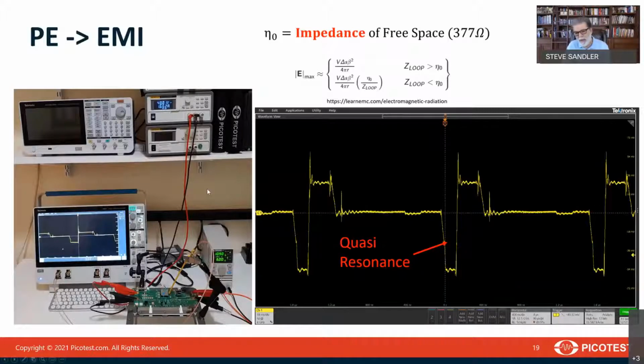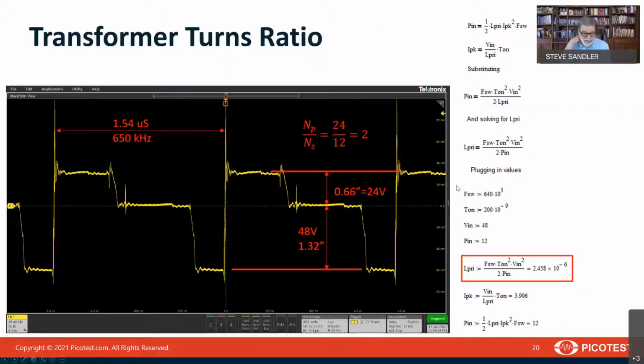One thing you might notice is the quasi-resonant edge, so you can see the near zero switching here in the resonant edge in order to improve efficiency. But we can also see where the switch is on, and we can see where the switch is off. We can even see the ringing in the transformer. And then, of course, we can see the plateau. This is where the power is delivered. So we were able to determine quickly that this is actually a flyback power supply.